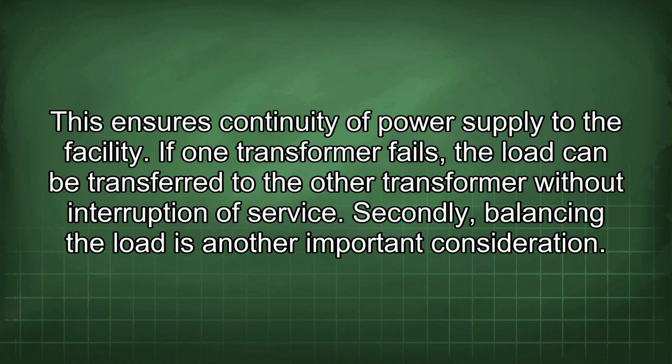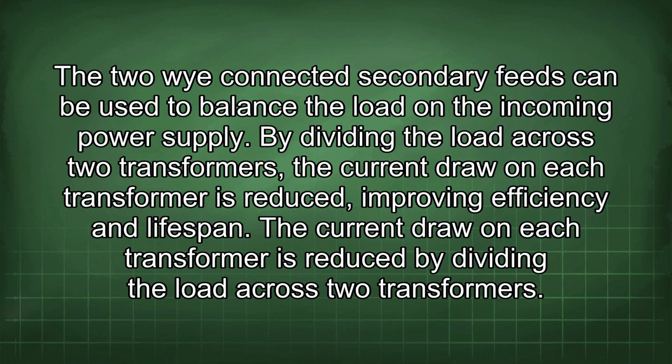Secondly, balancing the load is another important consideration. The two Y-connected secondary feeds can be used to balance the load in the incoming power supply. By dividing the load across two transformers, the current draw on each transformer is reduced, improving efficiency and lifespan.